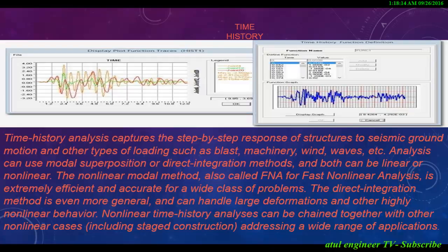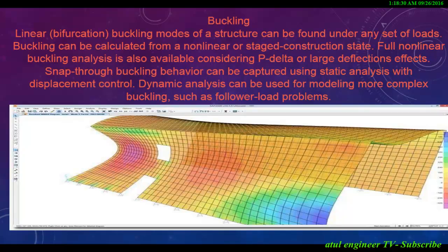The nonlinear modal method, also called FNA for fast nonlinear analysis, is extremely efficient and accurate for a wide class of problems. The direct integration method is even more general, and can handle large deformations and other highly nonlinear behavior. Nonlinear time history analysis can be chained together with other nonlinear cases, including staged construction, addressing a wide range of applications.